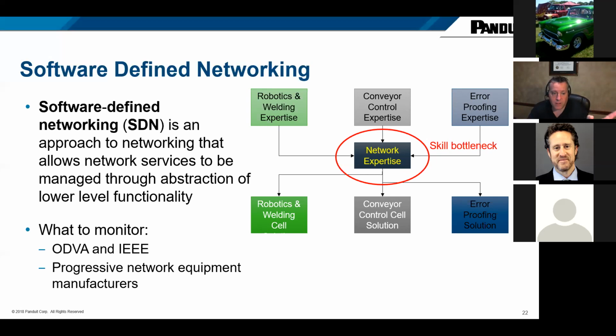I mean, probably talking decades before you really see software-defined networking. But again, plan for this type of skill set on the plant floor as it comes out of the labs and into actual product and technology and starts to be implemented in the field. Putting in that physical layer today is going to enable these kinds of technologies. So if you put in the proper fiber optic backbone today, we'll be able to easily migrate equipment here. You won't have to rip and replace in the future.